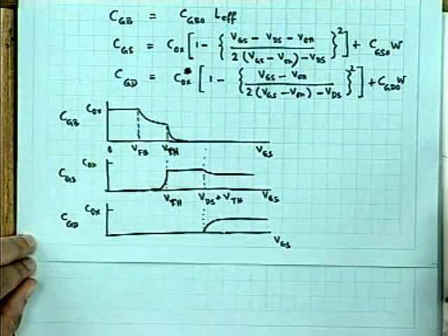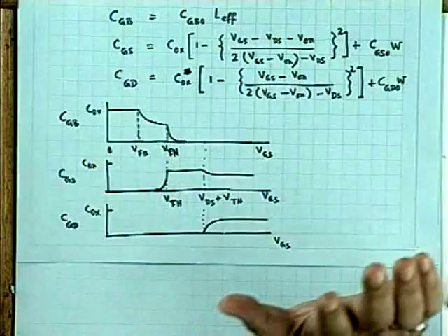One thing perhaps you know is that it's a very complex situation. When you think in terms of circuit simulation, you are applying say nodal analysis and loop analysis, whatever approach you feel convenient, and there, current in a branch now consists of two components. One is a DC component, the other is a transient or AC component.